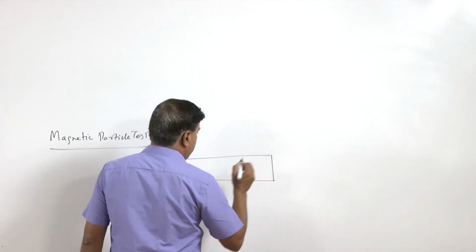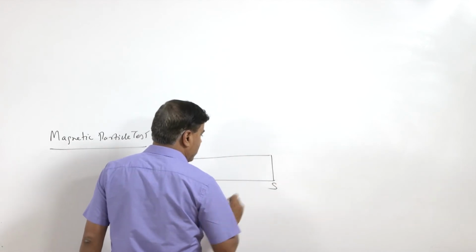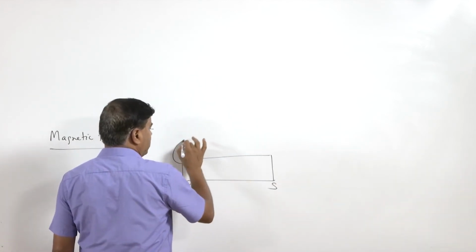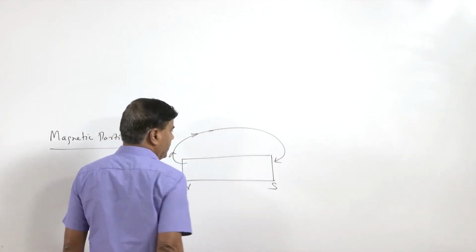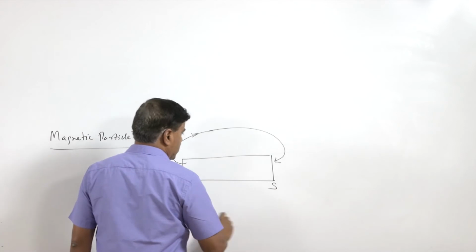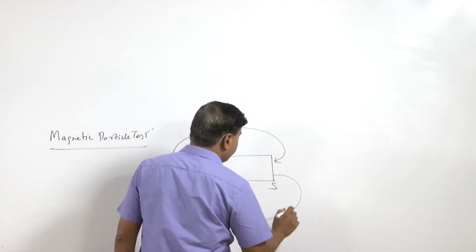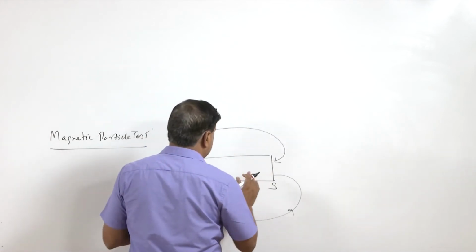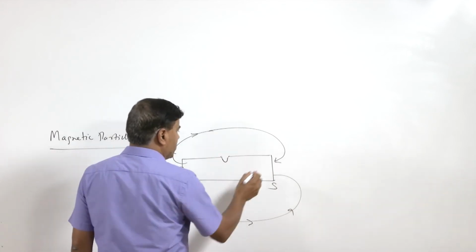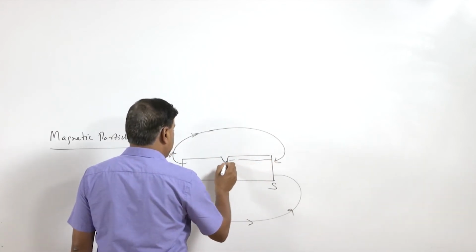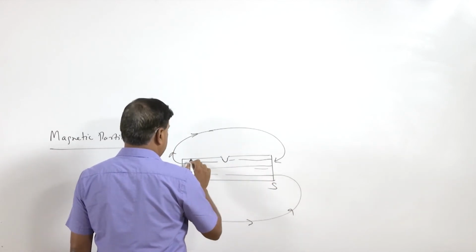know that in each magnet there is a north pole and there is a south pole. So, the magnetic lines of force take exit from the north pole and they enter through the south pole. So, this is what will be happening at both the ends. Suppose in this component, if we find any discontinuity in the form of cracks, so these magnetic lines of force will be passing through the component like this, right.